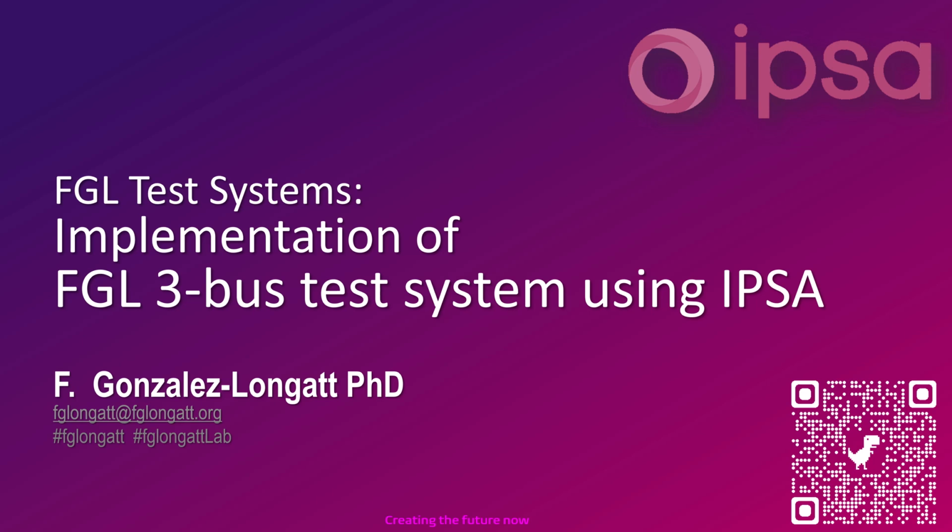And this video has been very interesting because we followed step by step the creation of the network, completing the data, configuring the power flow study, finally running the load flow, and we obtained some results. And the interesting feature about configuring the animated load flow has been presented over here.